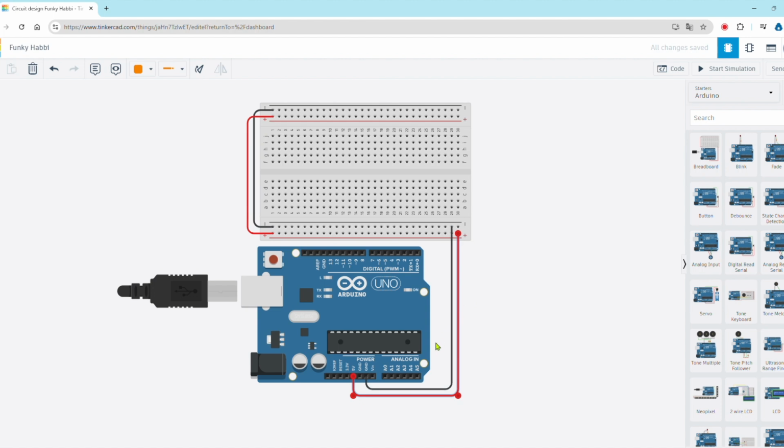You can select any of the elements available in the graphical area. As long as you have the cable option activated and click on a starting point, the cable design will start to be drawn by moving the mouse. Explore these features. As you can see, they are very intuitive and easy to use.